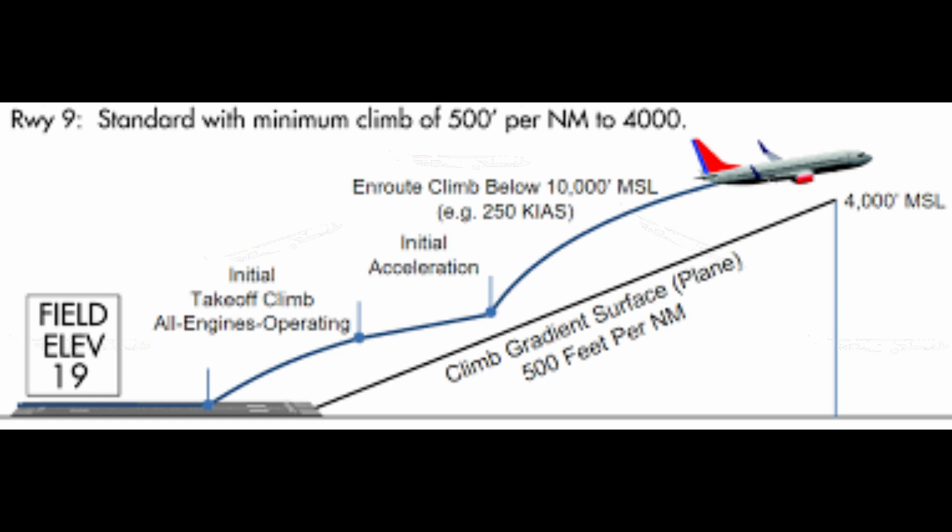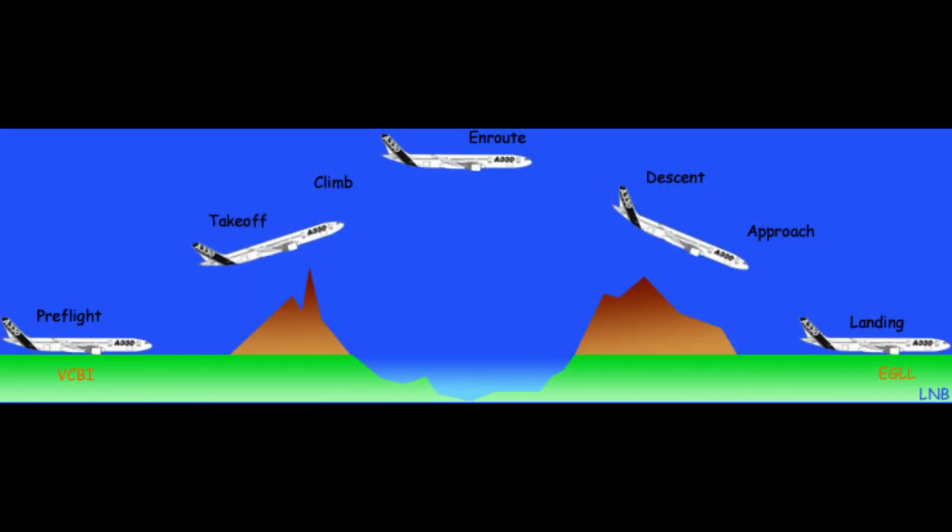Aircraft speed and altitude during the en route descent phase of flight. An additional benefit of FMS is that it provides fuel-saving idle thrust descent to your destination airport. This allows an uninterrupted profile descent from level cruising altitude to an appropriate MIA, except where level flight is required for speed adjustment. Controllers anticipate and plan that the pilot may level off at 10,000 feet MSL on descent to comply with the 14 CFR Part 91 indicated airspeed limit of 250 knots. Leveling off at any other time on descent may seriously affect air traffic handling by ATC.